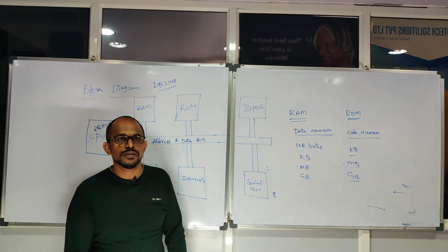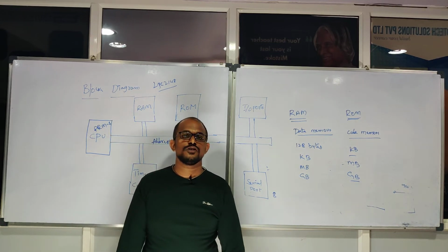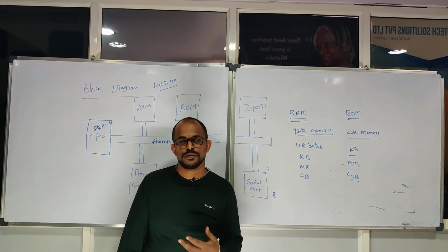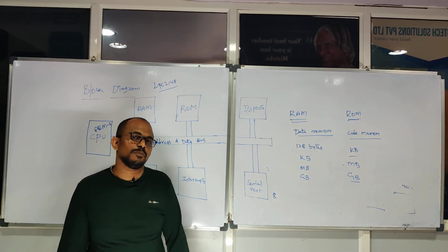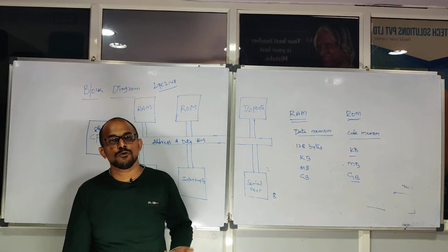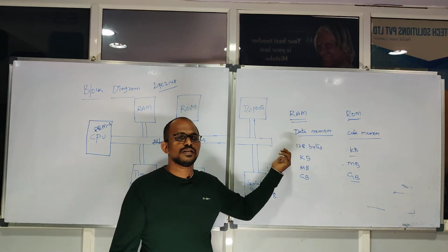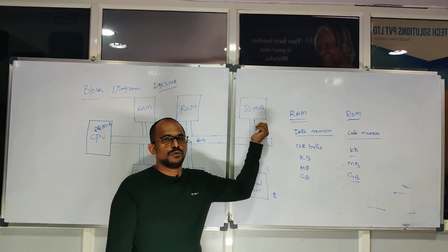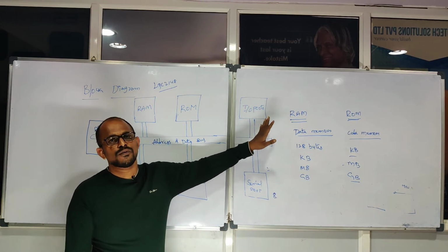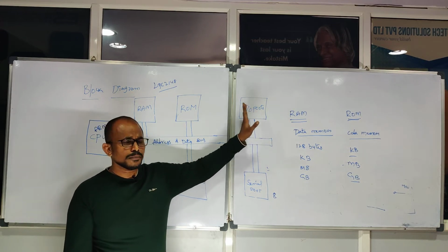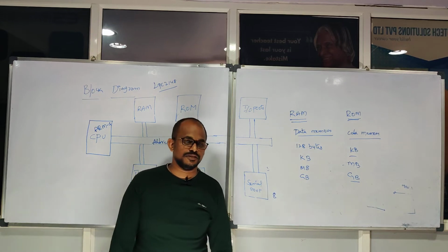And this IO port quantity also changes from controller to controller. In basic microcontrollers, you may have only 10 IOs, 14 IOs, 25 IOs, 32 IOs. But once you move into advanced families, there is huge support of IO lines, 64 IOs, 100 IOs. Depending on the application, they may choose different controllers. But any microcontroller will come with a standard number of IOs or more, and the IO ports' purpose is very clear: use it for connecting peripherals like sensors and displays.